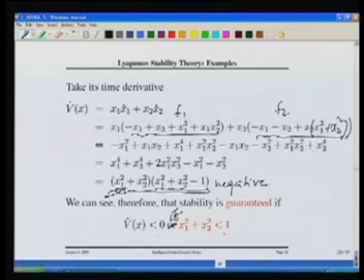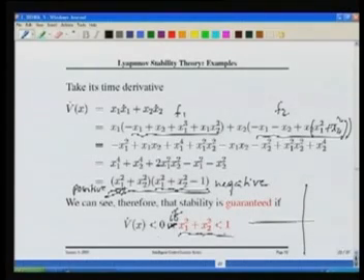This quantity you can always say is positive. So this will become negative definite if this becomes negative, and this becomes negative if x1 square plus x2 square is less than 1, and that is the condition for which the system is stable. So obviously this gives me the region of attraction, because this is my x1, this is my x2, this is my origin. So obviously this is a circle of radius 1, this r equal to 1.